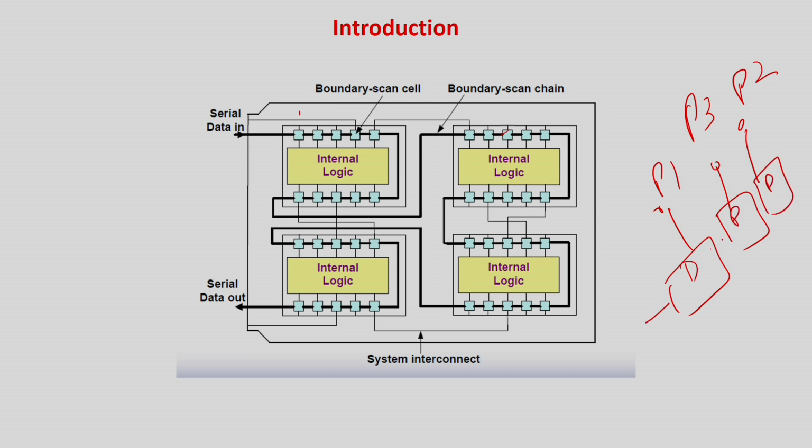So in a scan chain, what we do is put all these flip-flops in a chain in the test mode, and whatever values 1, 0, 1 are required at this point, we shift them in using the scan mode. Those values are applied, you can do the test, and again take back the response from the scan chain.